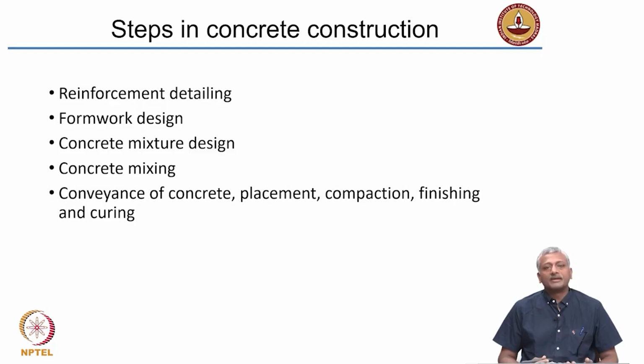Concrete mixture design involves selection of the right proportion of ingredients, primarily cement, water, aggregates, in such a way that they give a concrete mix that has a sufficient amount of workability, and of course it performs to the satisfactory level in terms of strength and durability. Now the process of mixing itself is important because ultimately these ingredients that you put in have to be intimately mixed together to give you a composite material that is having a uniform spread of different phases across the volume.